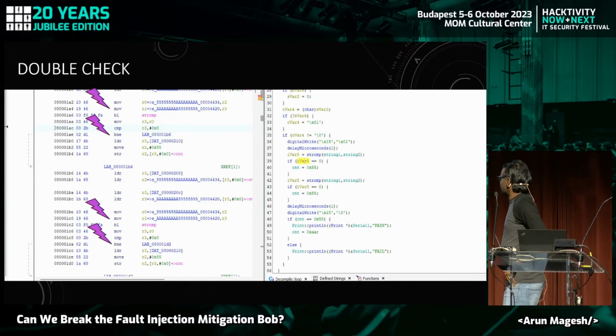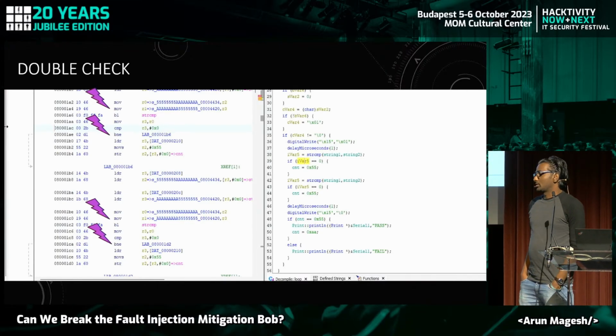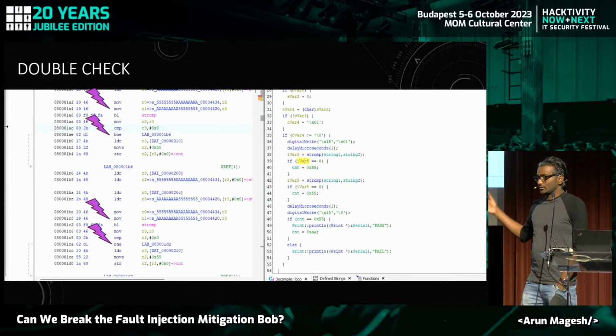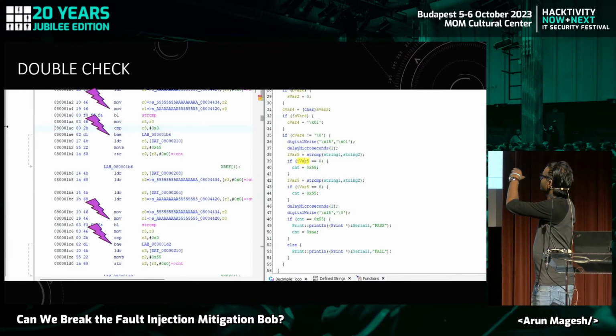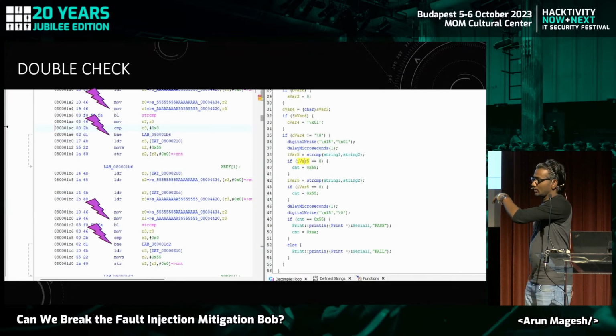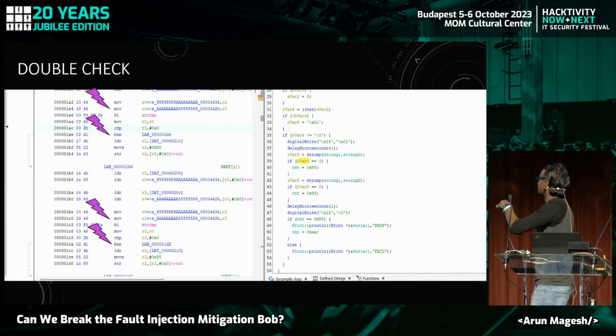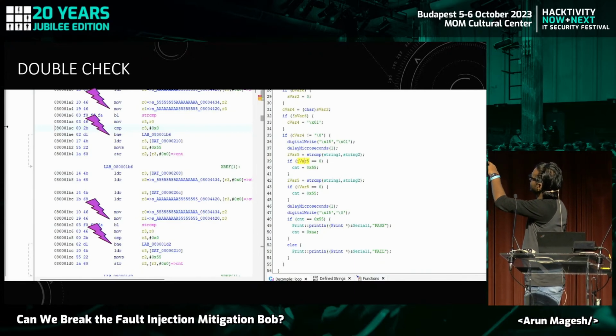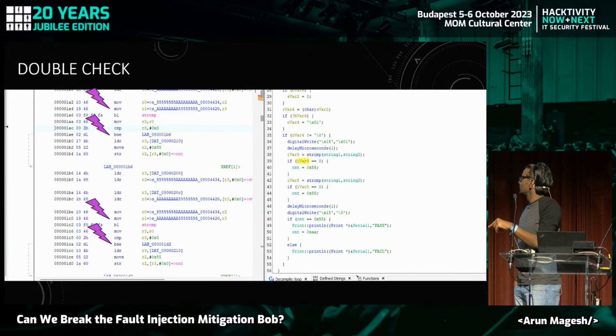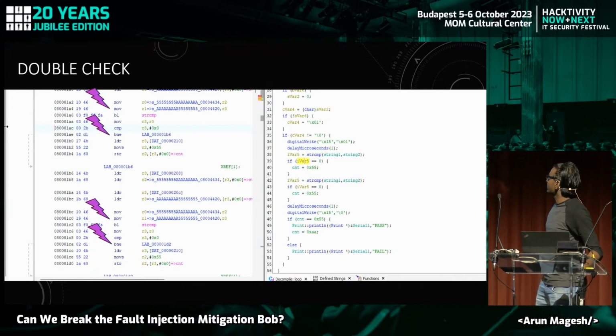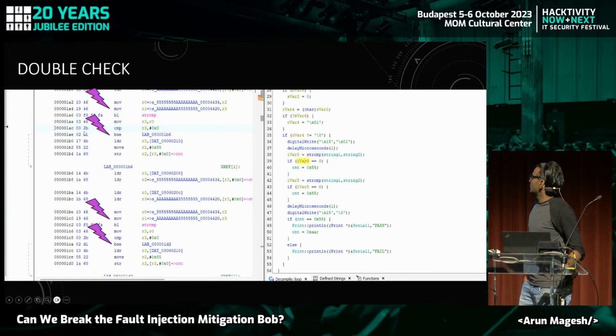Here, again, not much changes. Here you have 2, but again, you're missing the point that your last check is the main deciding factor. Even if you have your first one wrong, you can still glitch your second part, and whatever the model we identified is going to be the same, which means you just need to glitch at the second point. Or, if you're planning to glitch the branch instruction, you can also corrupt it so that it jumps to a different path. I think in ARM, you don't just jump with the address, you jump with an offset. So even if you glitch to add a few more addresses, you can make your PC go to a different offset, and then you can pretty much bypass it.